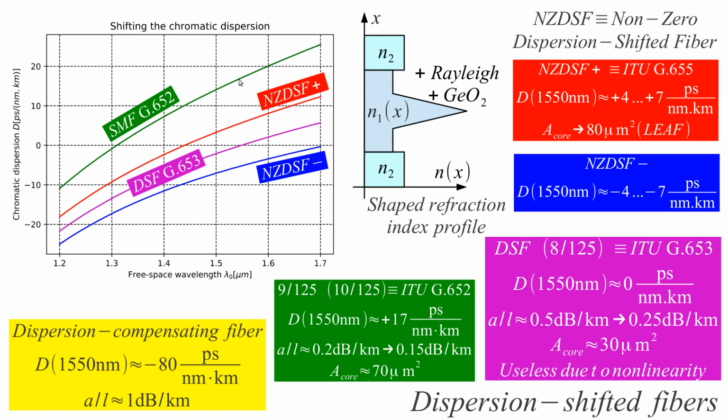So non-zero dispersion shifted fiber is a way in between, and connecting equal lengths of two such fibers in series, we can cancel out the chromatic dispersion completely without generating nonlinearities. These non-zero dispersion fibers were even designed with very large area cores, again to minimize nonlinear effects. This large effective area fiber was the discussion. Yes, this was for new installations, for new transoceanic cables.